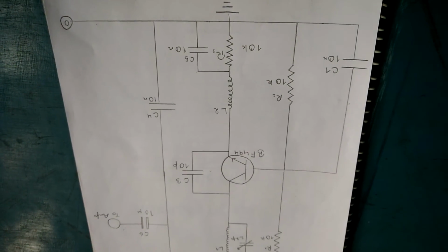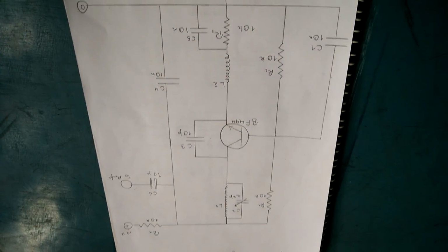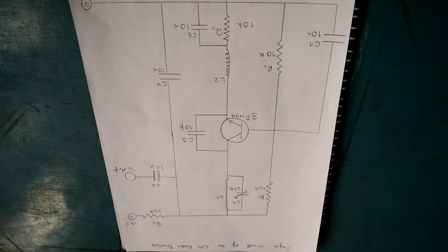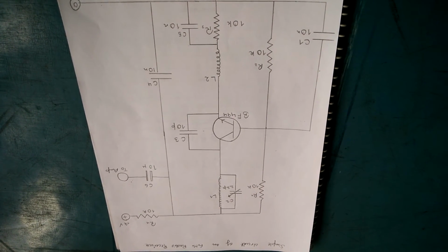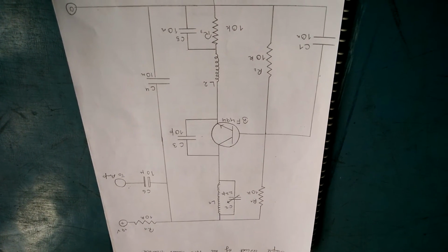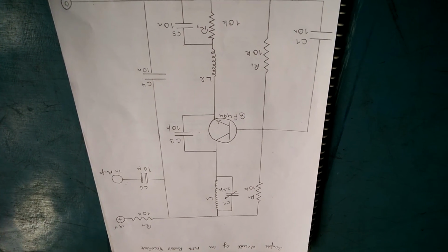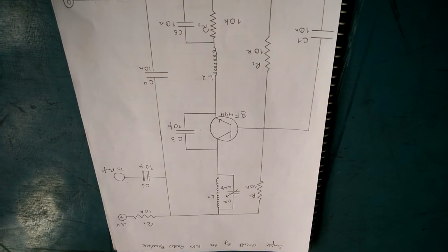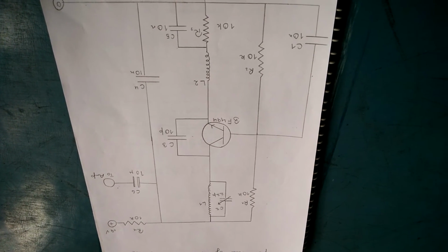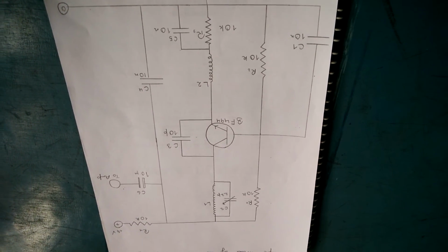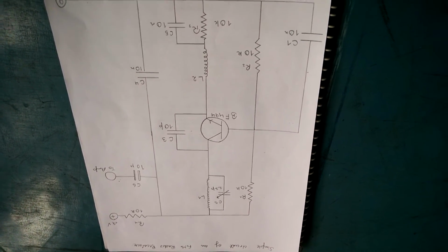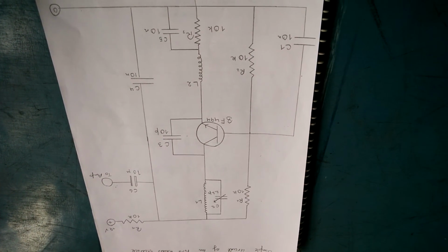A smart technique can be seen employed in the following single transistor FM radio circuit to attribute better efficiency to this simple design. Here we pull out the emitter capacitor C5 ground link and connect it with the output. This results in a fall in the capacitor voltage as the capacitor current rises, which in turn forces the emitter voltage to rise, prompting the emitter capacitor to negate the situation at the output. This enforcement results in making the sawtooth effect on the received signal practically zero, thus presenting an FM audio with much reduced background noise.